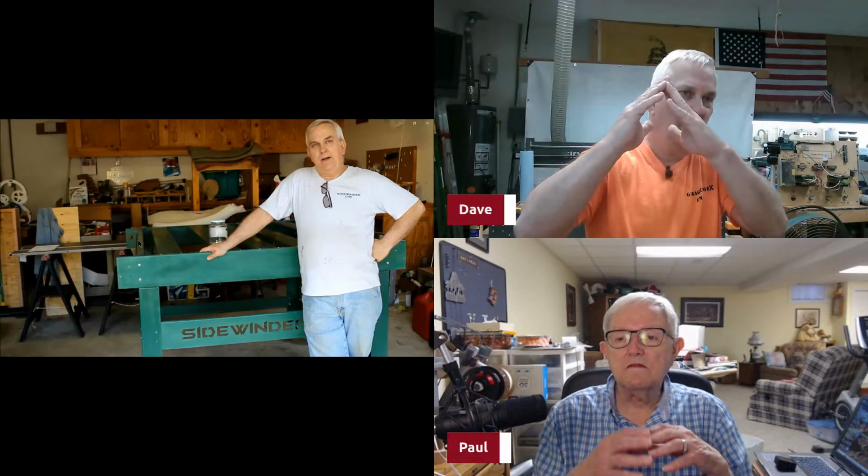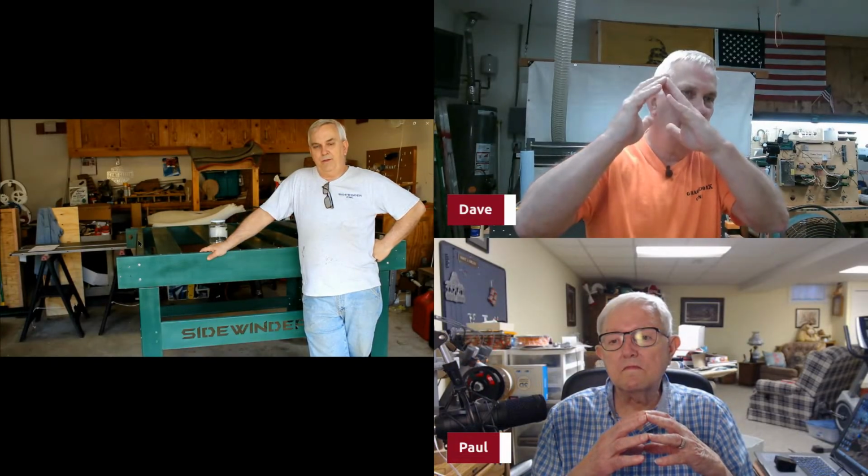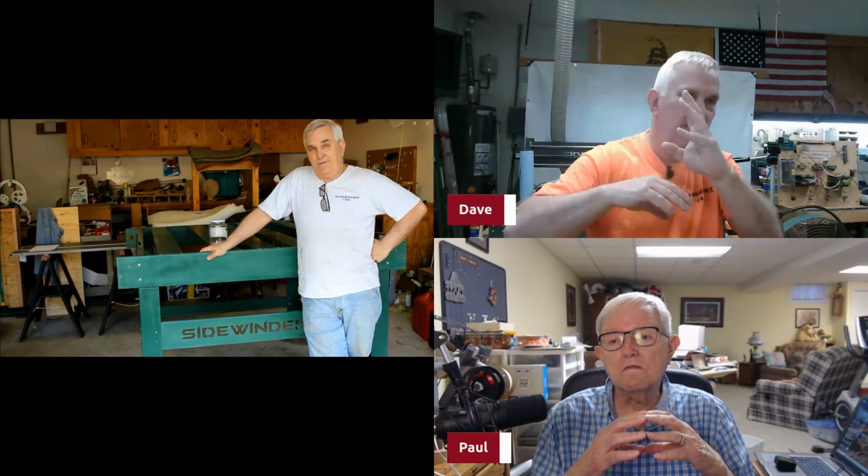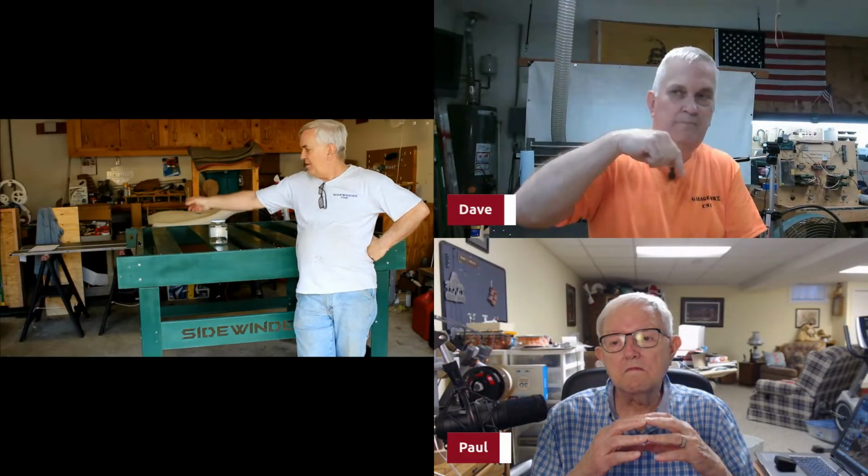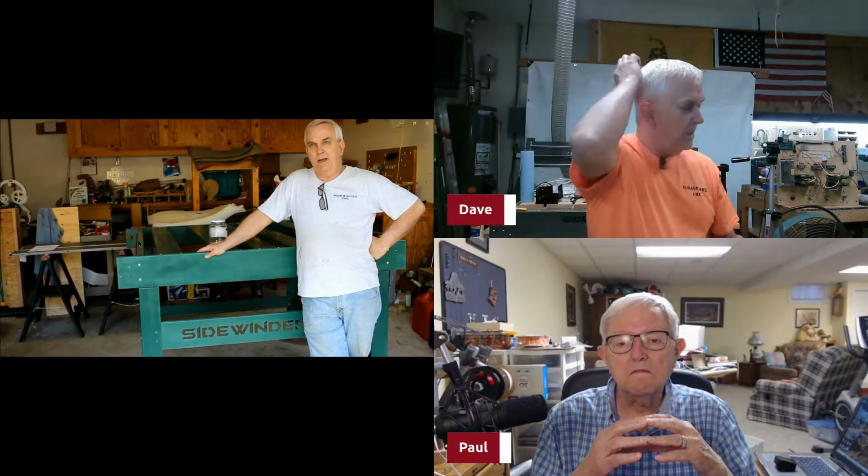And then if you look close, you might be able to tell that there's a rail on the side, you can kind of see it on this one here. And when I say rail, what it was some 1/4-inch flat bar that I had a machine shop put a bevel on the top and the bottom of it. So you would run V-groove bearings on the top of that.